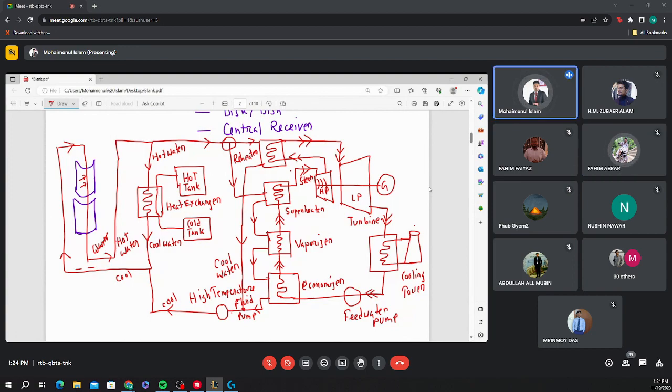Yes. So again, this valve, I'm just pointing to the valve again. This has another connection which flows to the superheater. The superheater is also another type of heat exchanger. That means you have heated or vaporized steam. You need to superheat that steam. So we can say the vaporizer produces steam. So steam is flowing in the upward direction. You need to ensure that the steam does not have any water content. So again, you reheat it.